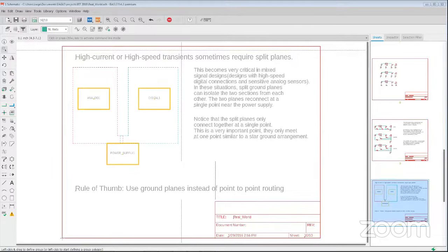So the impedance changes because you have a change in distance between the plane and the trace. So in the general case, adding multiple layers is going to change the numbers a bit. You do have to be aware of it if you're trying to match some exact value. If you just need a consistent impedance profile, then that becomes less important.